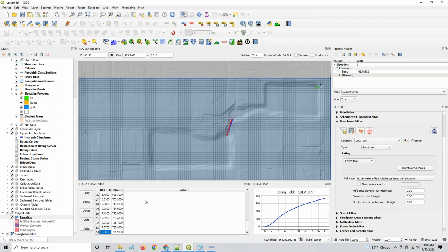Also, another thing you don't need, and it's written as 0, is this: unless you have a culvert that's, say, 1,000 feet long and you really care about the travel time and the volume in that culvert. If you do care about that, then this would go up to 1,000, and this would be the diameter of the structure, which I think in this case would be 4 feet. And then you would need this volume